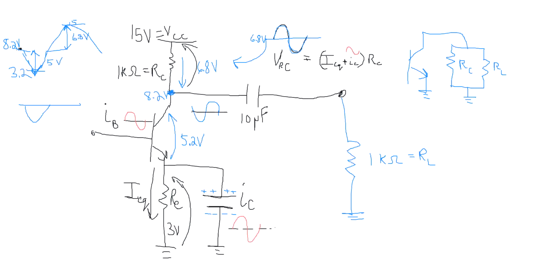Now, that might have seemed like a little bit of magic to you, so we're going to make it something that you could actually figure out on your own. So we're saying that our down peak here, our low peak is only halfway, and we could see that because we did some simple math, and we saw that at half the voltage, I'd have the full current, the 5 milliamps that I had before.